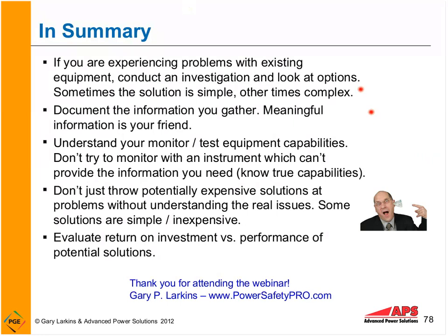If you have existing equipment that's experiencing a problem, conduct a thorough investigation. It may just be a simple loose connection in a wire. Document the information you gather. Meaningful information is always your friend. Always understand your monitor capabilities to make sure you're using the right monitor. Don't just throw expensive solutions at problems without understanding the real issues. I don't think anybody has money coming out their ears to be able to throw at problems today. And evaluate the return on investment.